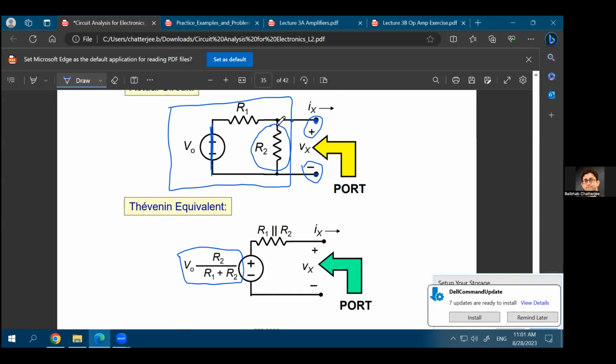And you look at what's the effective resistance looking into this port. One way to do that is to put a voltage source over here, let's say a Vx or a Vtest voltage source, and try to measure how much current is going. But we have already looked into that, so that's your nodal analysis that you have learned in 3111. But we already know from the previous two lectures how to find the equivalent resistance looking into this port.